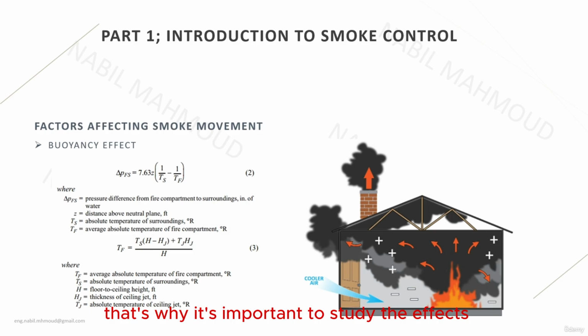That's why it's important to study the effects of the buoyancy effect in case you are applying a pressurization into a specific volume or a specific enclosure that is expected to have a fire scenario. Because if the buoyancy effect is exerting a positive pressure in the space, which has a higher pressure difference value than the value you are using in the pressurization system, it will almost cancel out the pressurization system. That's why it's very important to cross-check the pressure difference that is resulting from the buoyancy effect in case of a fire.